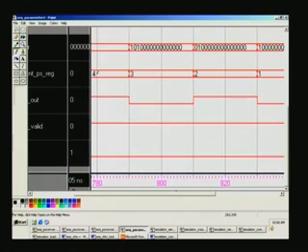Finally, we will have one more waveform where you see the end of this left shift. You can see again it was at 4. So, it is a left shift. So, what you have is one must get dropped, and one must also go through the output, and this is taking place here, because shift happens here, but it will get reflected only at the positive edge of the next clock. And so on it goes. You can see here this 0 1 comes over here, and all vacated bits are filled with zeros.